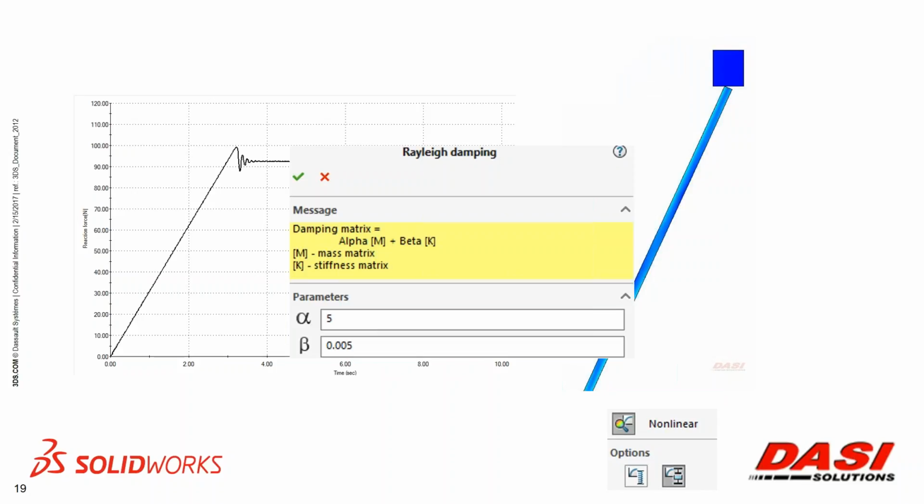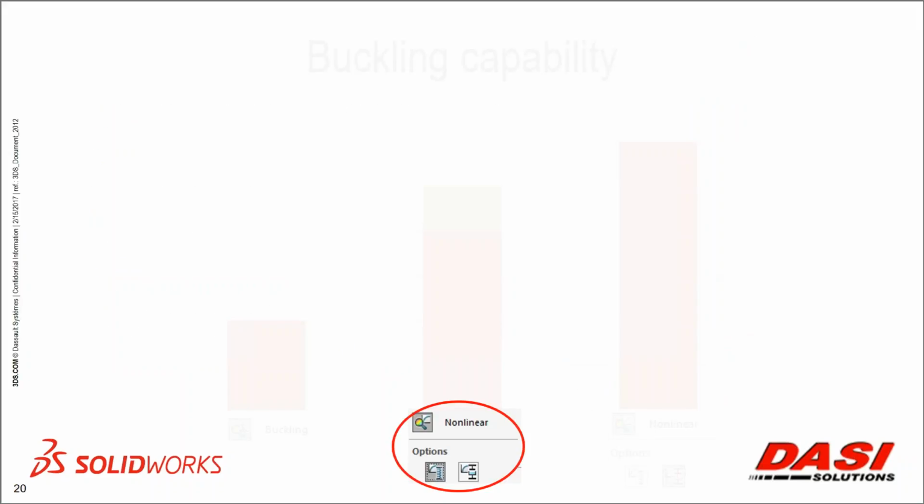So now, like I was saying, with nonlinear dynamic, you'll have to make some assumptions, maybe scale this damping factor up and down, exactly what to key in for the damping factor. You'd have to play with it, and there's a few other things. It can be a little more complicated to set up compared to the nonlinear static.